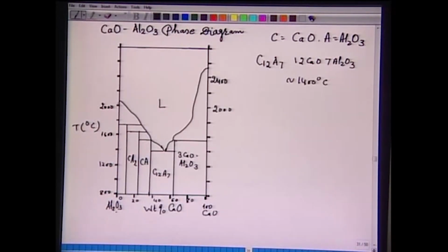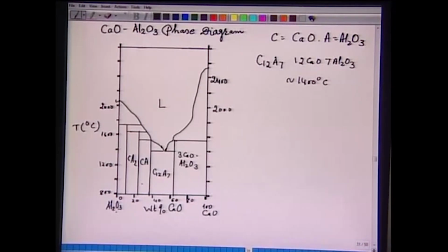Note that pure Al2O3 has a melting point of around 2050 degrees Celsius, which is solid at the steel making temperature. It is very difficult to remove. So, if we do a calcium treatment, a composition is reached where the melting point becomes minimum, and this composition is 12CaO 7Al2O3. There are other compositions too, for example CaO Al2O3 and CaO 2Al2O3, all with melting points higher than 12CaO 7Al2O3. So, by calcium injection, the aim is to form 12CaO 7Al2O3, which has a very low melting point. In fact, it is liquid and it can be made to float. That is the important point in the modification of alumina by calcium.